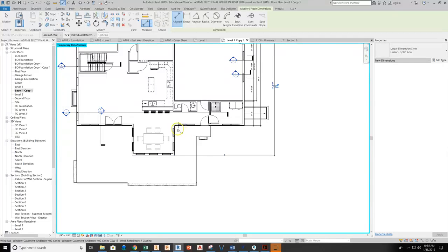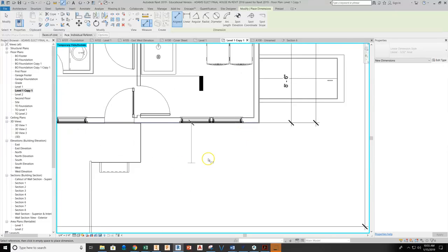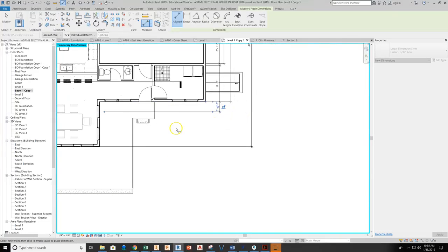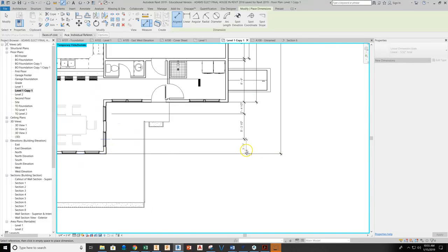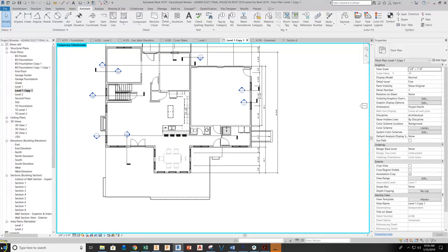And as I go, I can see that I need to do some dimensioning on these windows. So again, I'll go from sheeting face to center of window and pull those out to here as well. And then center of window, and you can see how this process just repeats itself all the way around the structure. So with that being set up, it seems fairly simple now to go ahead and cleanly dimension your drawing, and you just keep working your way around.